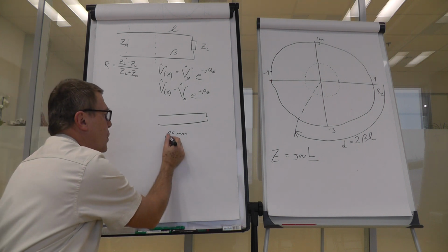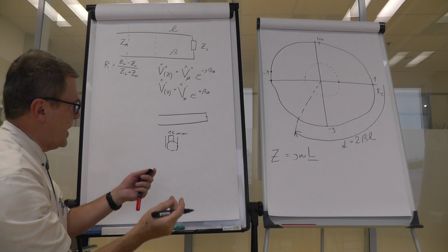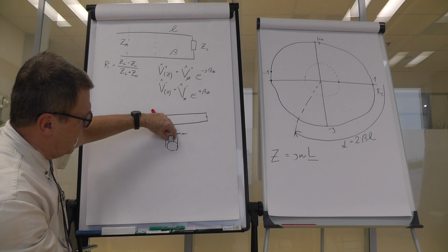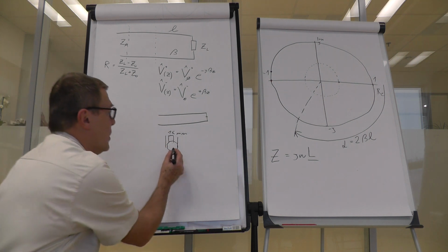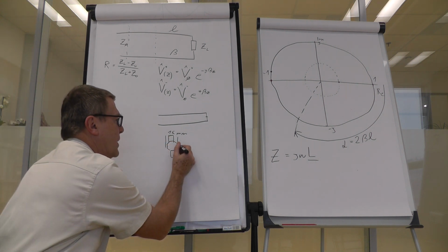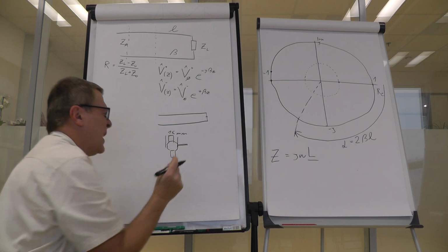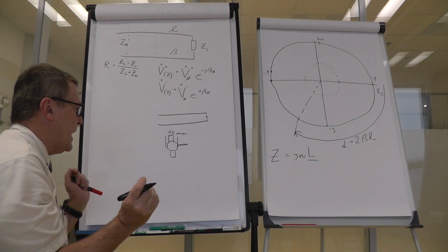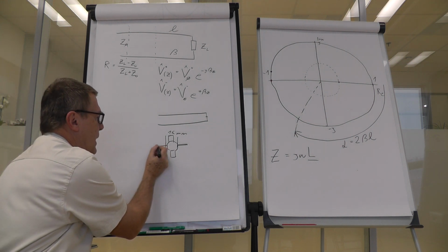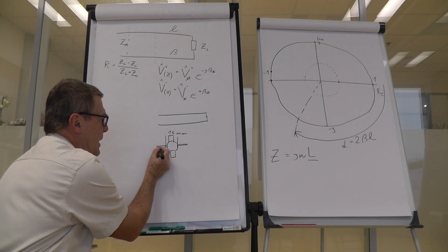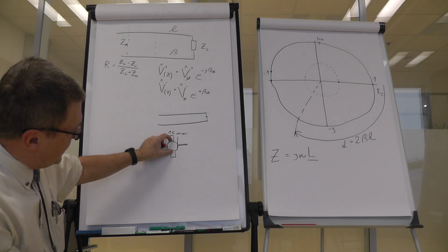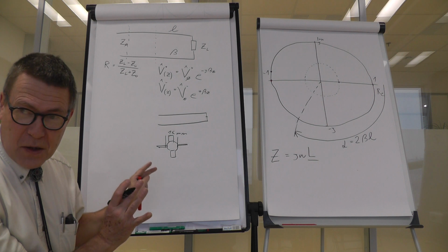So we have got 2 leads for emitter, which is a sheet of metal of, let's say, 1 millimeter in width. Those emitter pads are doubled on both sides, and then you have a collector, which is very thin. It's not a wire. It's again a thin sheet of metal, and the emitter, gate, is mostly made this way so that you can distinguish which is which. So this is 1.8 millimeters, so this whole thing is not very big.